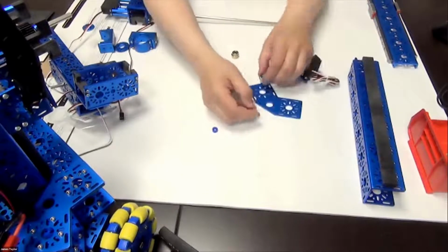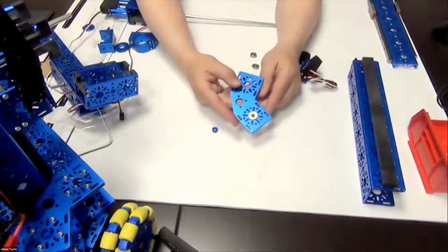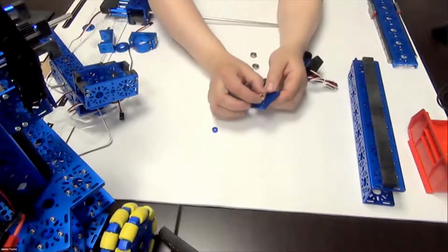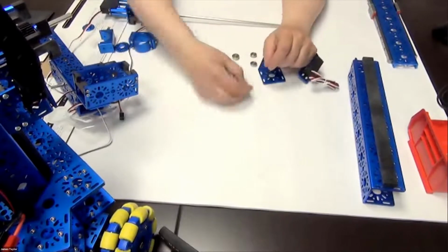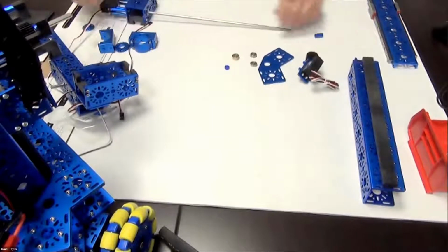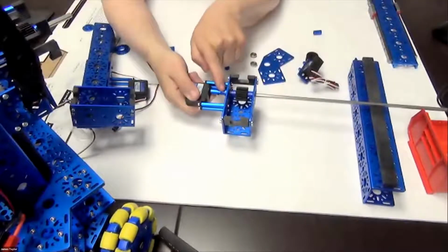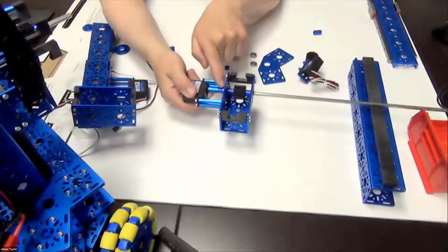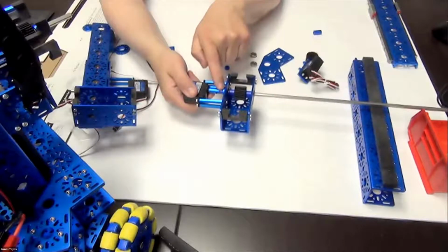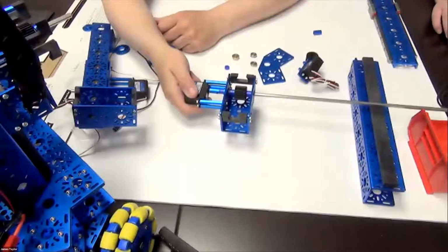The bearings pop in. It's the same thing if you're asked to use a bushing on one end. The bushings pop in as well, and then the shafts can go through. Your collars themselves will also be there. You can use multiple shaft collars if you want. In this case, there's a small shaft collar on the inside. Just watch your set screws. Always check your set screws. As part of your robot maintenance, for instance, after each time you do a run or work on your robot, you should check those set screws to make sure they're tight.